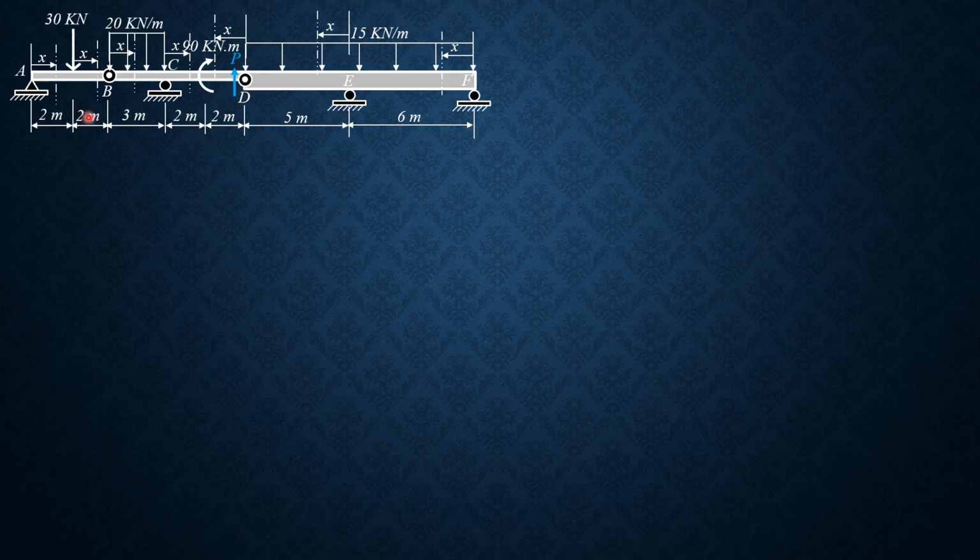So let's apply it here so that the reactions here will not be affected by P, so it's still 15 and 15. So action reaction 15, while the reaction here will not be a function of P, because if we sum up moment about D, the moment arm of P about D is 0. So this is still 86.25. Therefore, the moment equation up to this section is not a function of P. So we drop all the integrals for these 4 sections here.